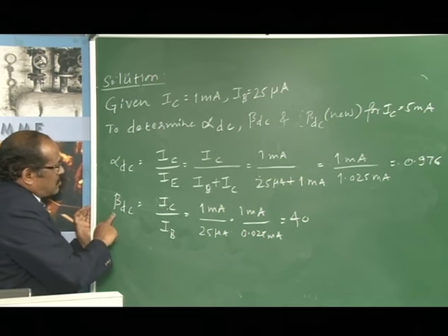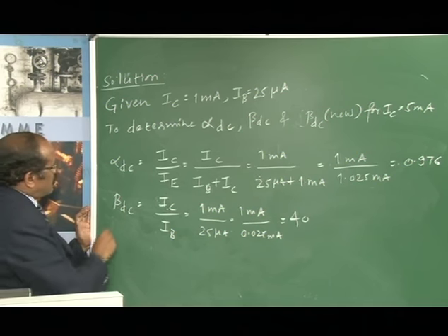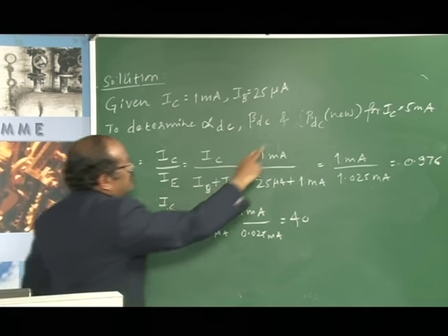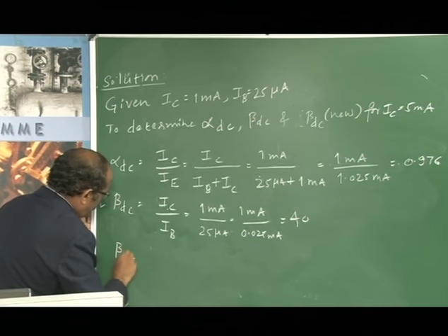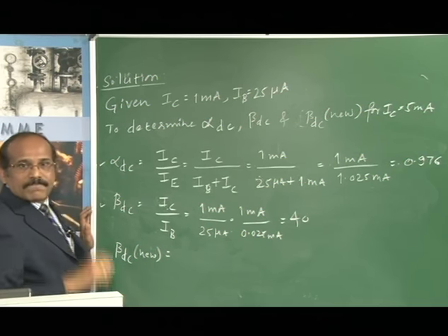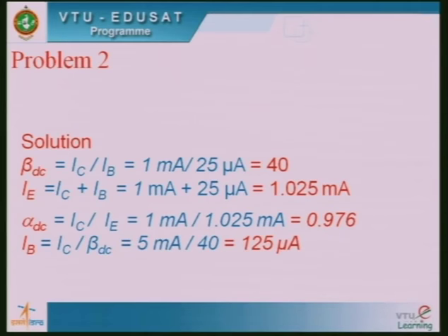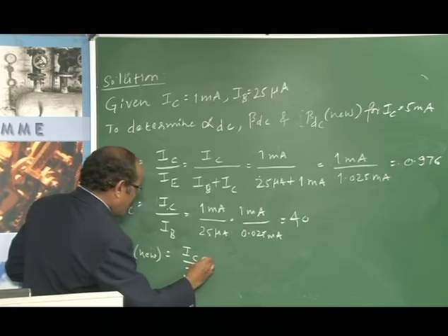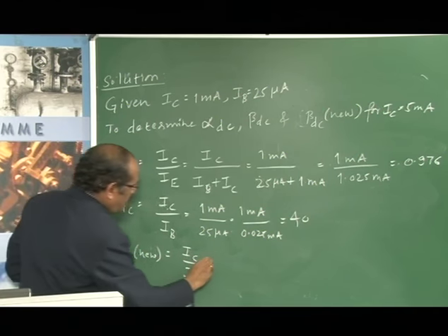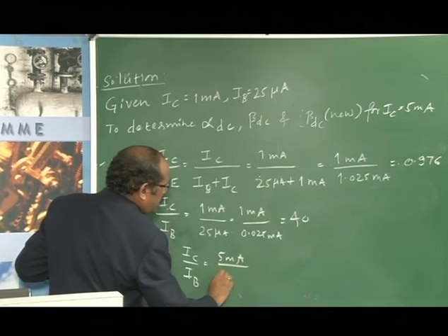Okay, so emitter DC current gain is what we are getting. Finally, using this data, what you need to do is find beta DC. As you know, we have used this once again, so beta DC for IC equal to this. Beta DC is nothing but IC by IB. So for IC of 5 milliampere, IB remains the same.